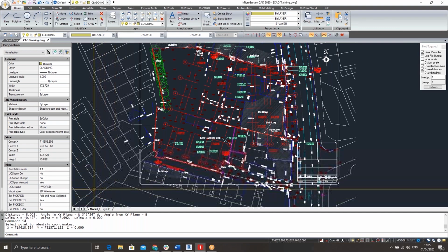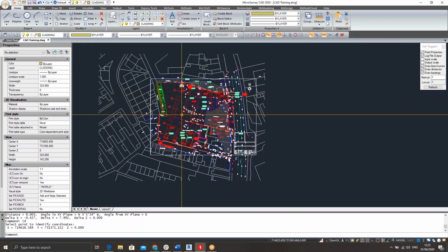Another point to note is that we can see the Z is 0. So it's a flat 2D drawing. Okay, so again, if you're trying to bring in 3D information, whether it's for setting out for roads or you want to input into a machine control, you need to identify first whether your information is in 3D or in fact 2D. The majority of the time, most setting out on sites is in 2D, but again, we just need to understand our drawing and make note of these things prior to bringing them into our field software.